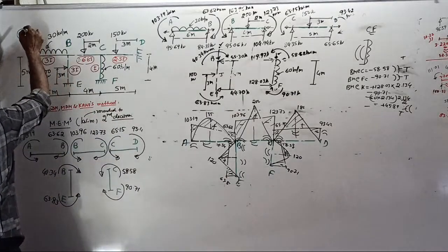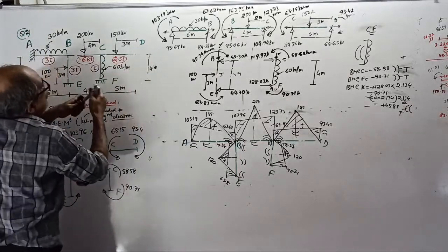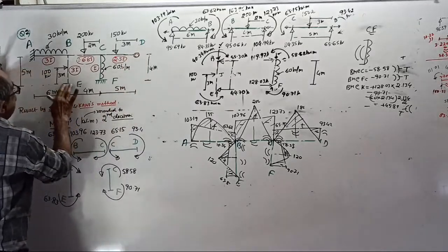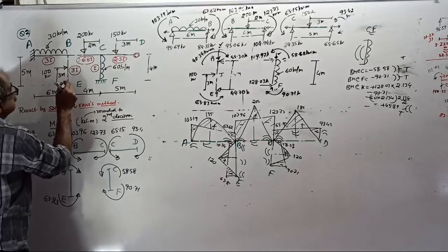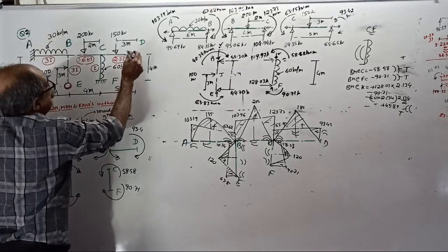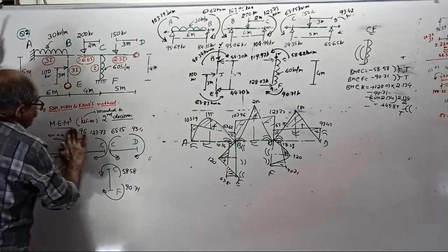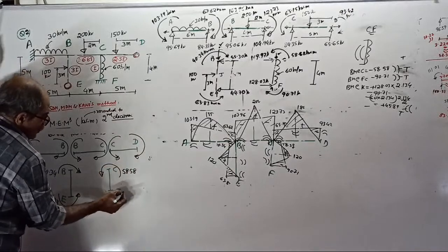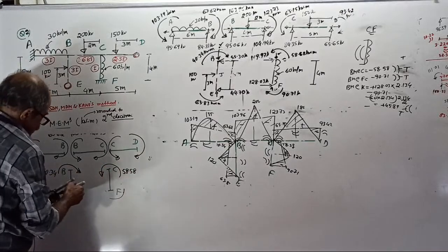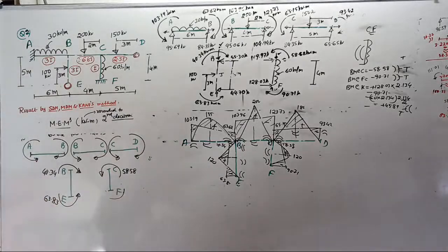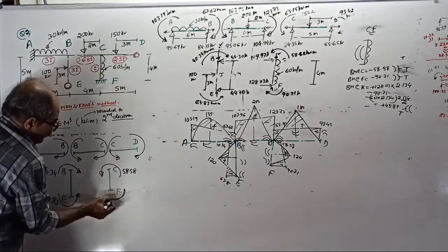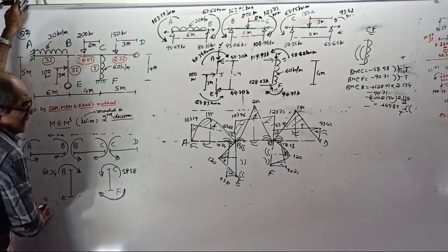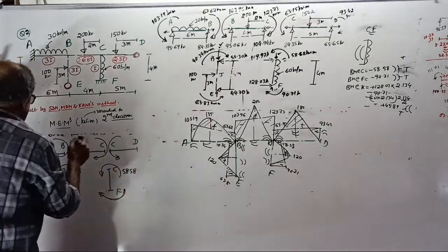Question number 2 has this support hinged end. This is a hinged support, and also this is a hinged support. Therefore, the moments are going to change, and this moment is coming 0, and this is not 0. A moment is there. I will give the moments so that you can start. This moment is 0. The moments I noted down there: 111.01.